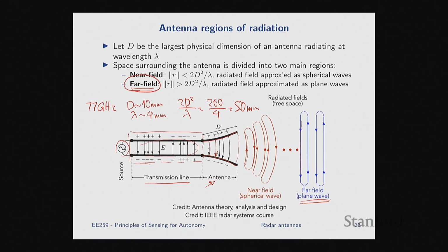From here on, we always assume everything is in far field, because for robotic applications those are the typical scenarios. Now, having said that, if you are working on an application where it's near field, everything we say wouldn't necessarily apply, so you have to correct those assumptions. But it's absolutely not the case that radar does not work in near field. There is near field radar, and it works beautifully, but the signal models are different, the DSP is different, the physics is a little different.